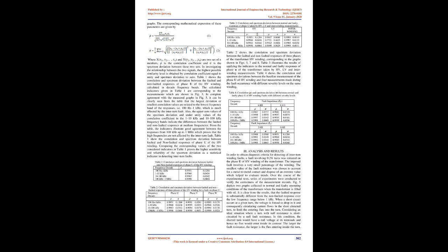A close view of the considered transformer's HV windings and tap positions of the introduced fault, before and after refilling the oil to the transformer tank, is given in Fig. 4. A. Before refilling the oil. B. Side view of the transformer after refilling the oil. Before conducting the experiments, a full load test was performed on the transformer with the taps open to verify that the modifications had not changed the transformer's normal operating characteristics. Once this test was completed, selected fault scenarios can be initiated to make the SFRA measurements.